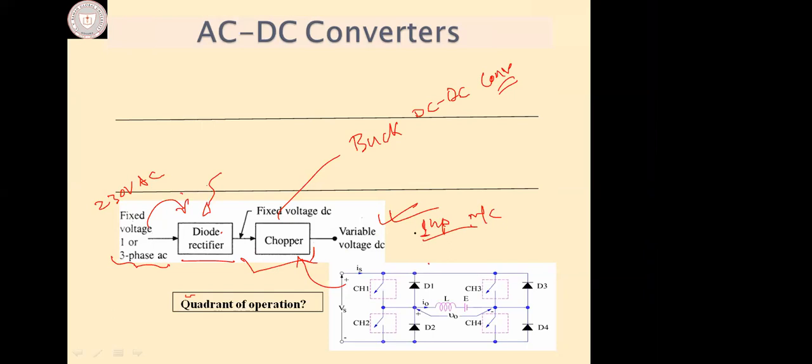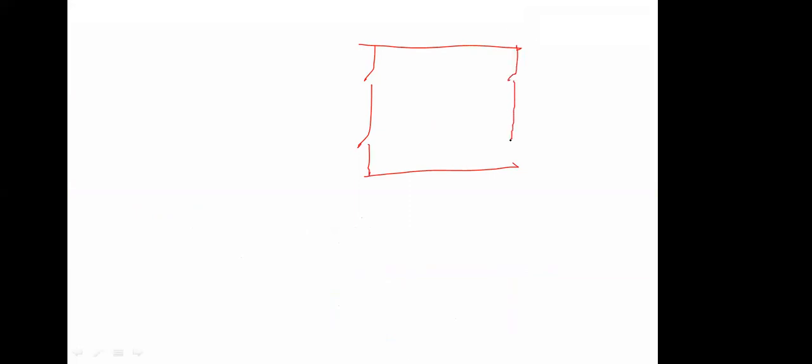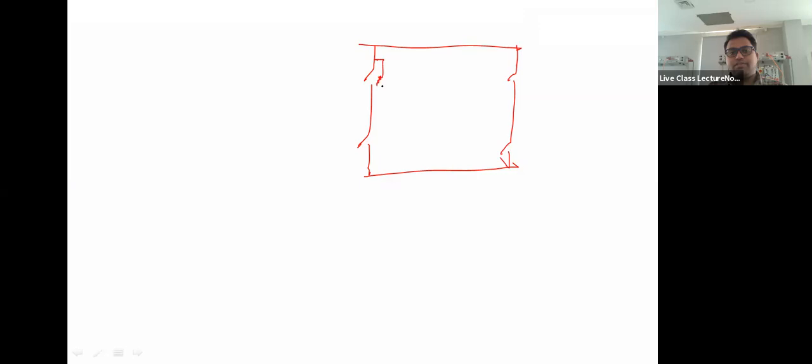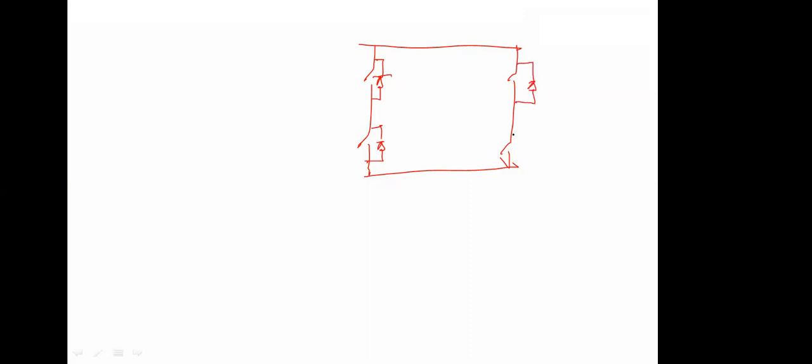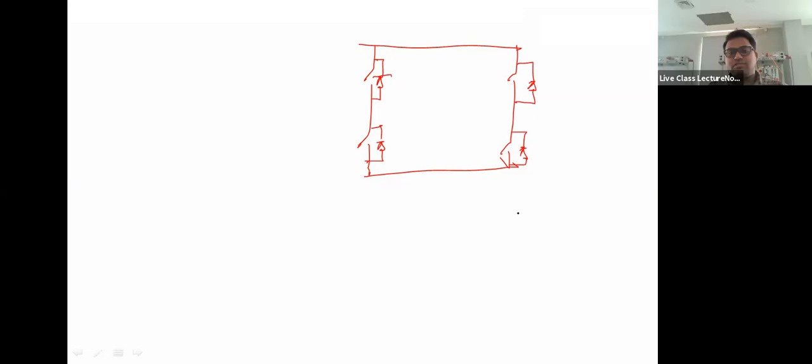Can you explain that circuit again, sir? Yeah, sure. First of all, in order to have a 4-quadrant chopper, what is the circuit? And with each switch you have a bypass. No, this is not a thyristor. This is a bypass, an inbuilt body diode. Actually, this switch is an IGBT or a MOSFET.